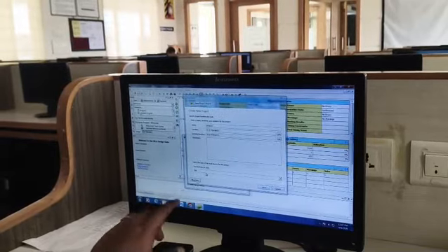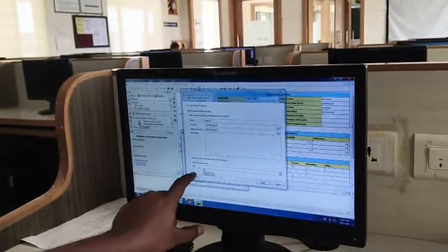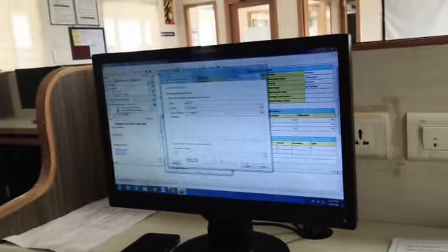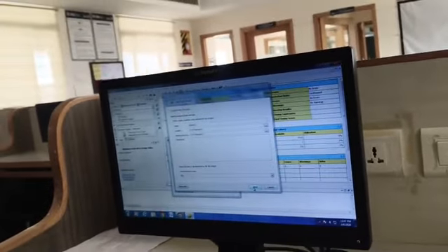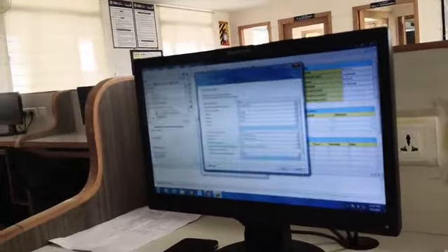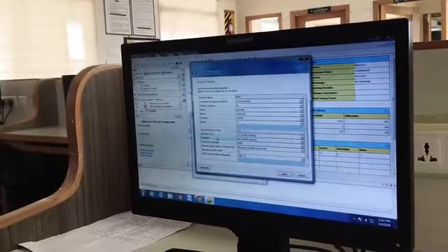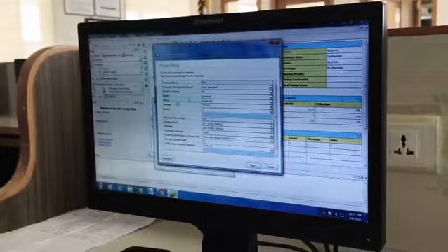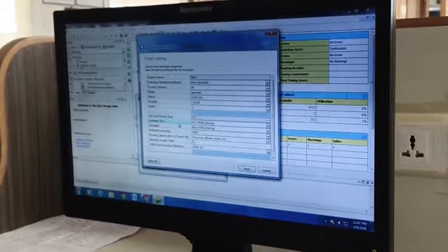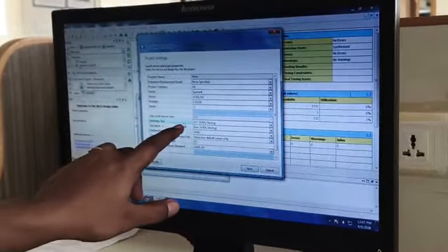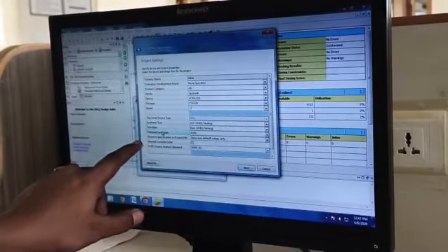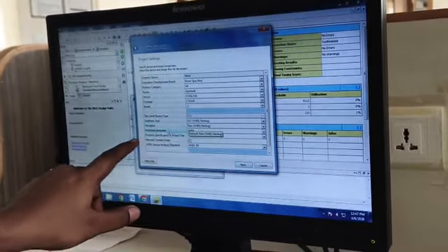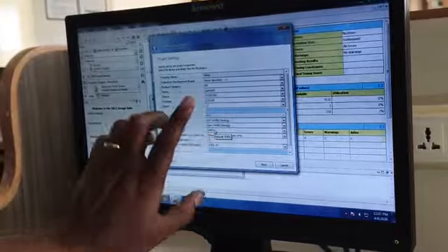Again ensure that HDL is selected as the source type, then click Next. Here we have to look at three parameters. The family and devices above are fixed, that's okay. Ensure the synthesis tool is XST, the simulator is ISim, and the preferred language is VHDL.